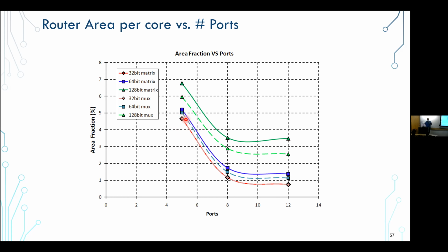Right? So my area requirements on the whole die, if the whole compute die is area limited for yield reasons, then if I have these 5-port routers, I'm actually hurting the computation. And remember, I'm also hurting the latency of the whole thing because a full mesh 4x4 is actually going to have the longest latency, right?